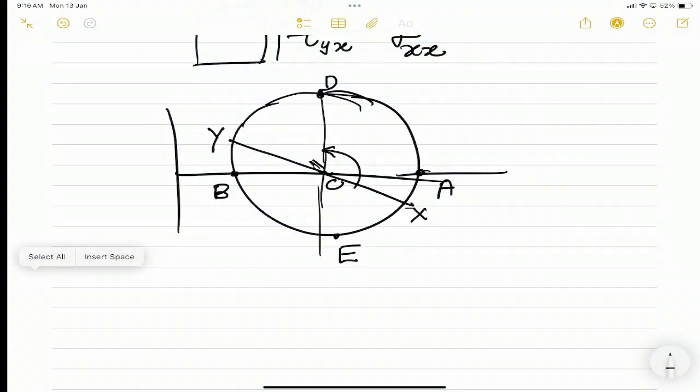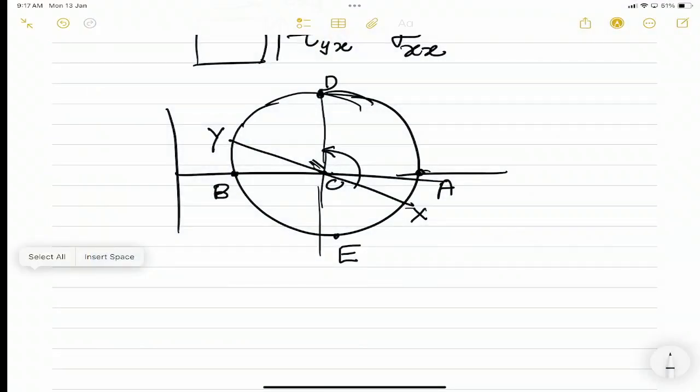Now this angle from X to D will give me the location of maximum shear stress. Now just as I showed that the brittle material fails when the normal stress is maximum, a ductile material fails when the shear stress is maximum. So for finding the failure of a ductile material, we have to locate the plane where the shear stress is maximum. So now this angle XCD, we call it 2 times theta s.